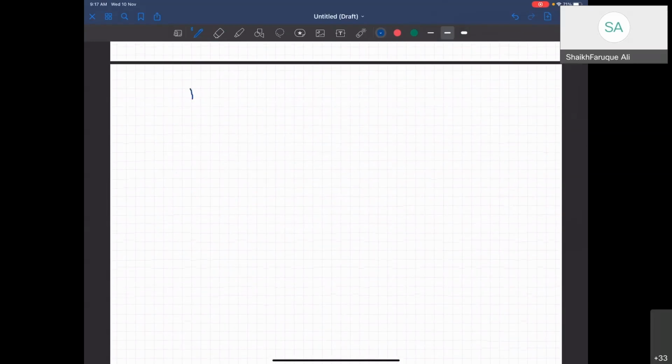So let's go back to our basic analysis. We have the channel section here, and we can calculate shear flow, and the shear flow will give us a force, which is this one, FF, this one here, FF, and here it will give a V force, right? Okay, and let's say I have attached a gusset plate here.